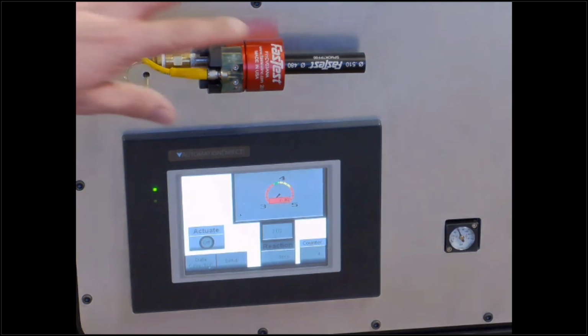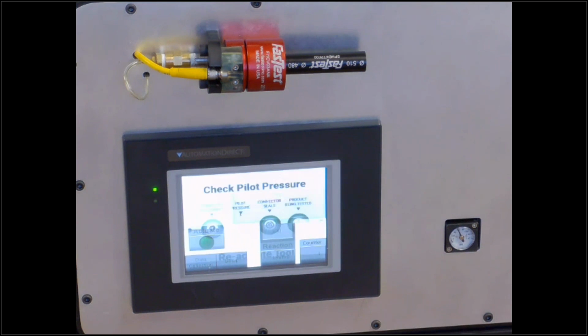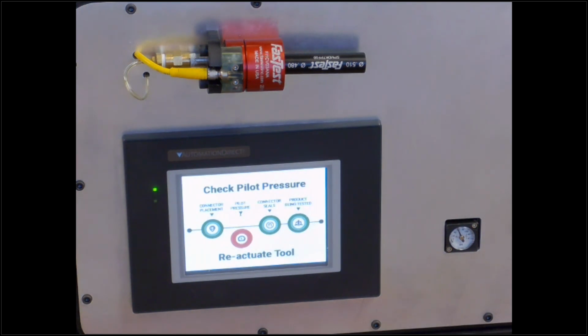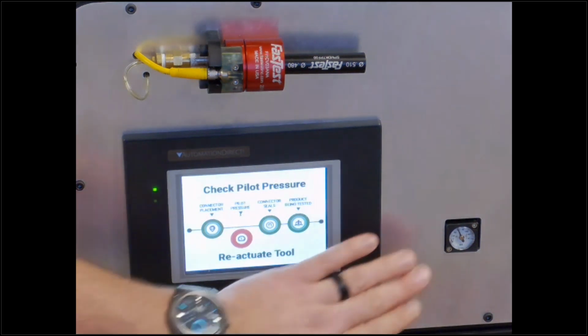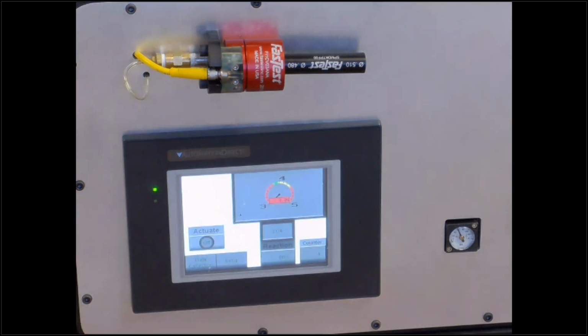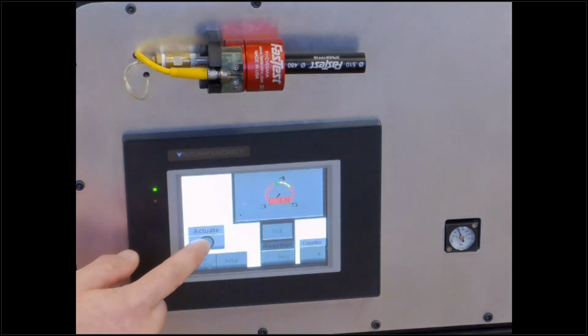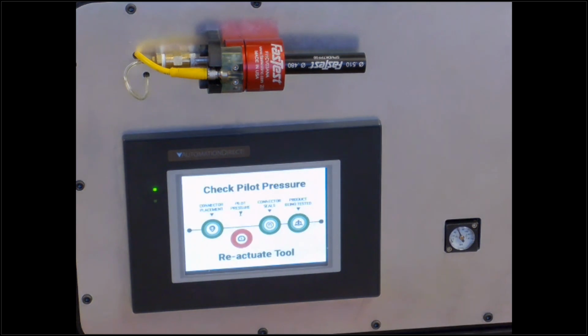So I'm just going to use this smaller end of our test piece to really highlight what happens in an under travel condition. If I hit actuate, it doesn't get there. And now I've got an alert to the operator to check the pilot pressure and reactuate the tool. We've got a pilot gauge there, and that's good. So I'd say, well, I need to reactuate that. And maybe the operator put the device in the wrong port or something like that. So again, if I actuate, it doesn't get where it needs to go, and immediately says check pilot pressure. So this is that instant feedback that there's something wrong with that device.